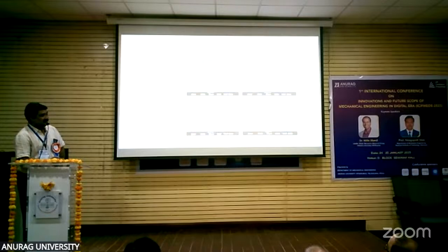Now it is the same specimen, and it is clearly observed that it gives clear microstructures. The first one, with clearly bigger grains, is the base material. Then structured grains appear in the heat affected zone, and mixed structures appear in the thermomechanical heat affected zone. Finally the nugget zone gives fine grains.